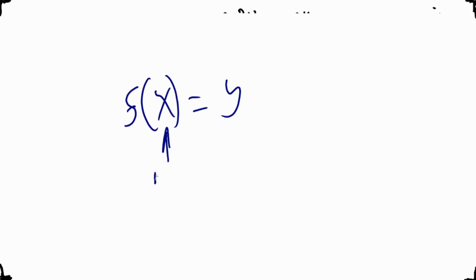So if it's 20 degrees, we don't know if the thermistor would be 100 ohms or 1,000 ohms or what the story is. We want to generate some kind of mathematical equation, f of x is equal to y, where f is a function and x is the resistance. Well, not actually the resistance, the voltage technically, because we're measuring the voltage, not the resistance.